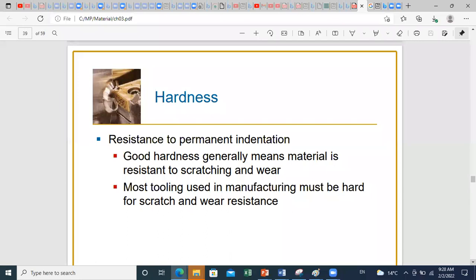Here the elastic region is very limited and the material will undergo failure at very small values of strain. So sometimes it's complex to measure these values in the case of a brittle material. So for more accurate results, we prefer to do the test as a bending test. Okay, thank you. Welcome.